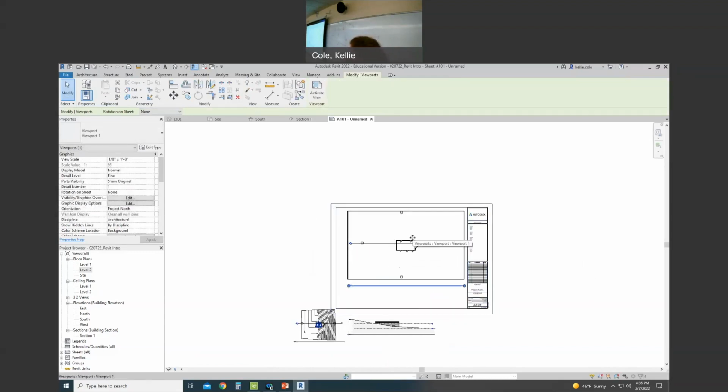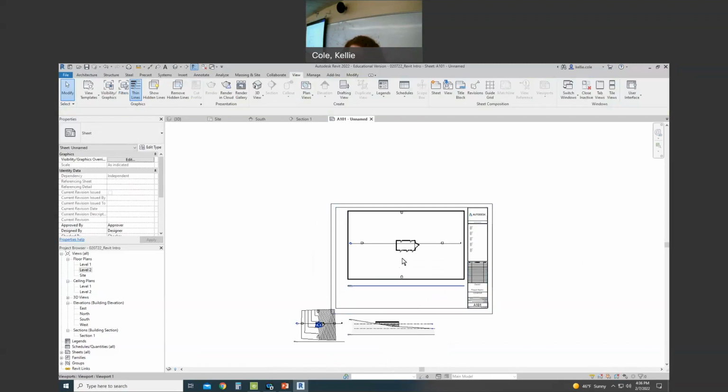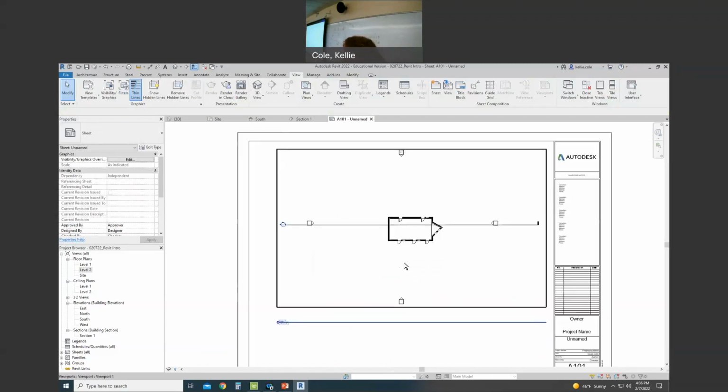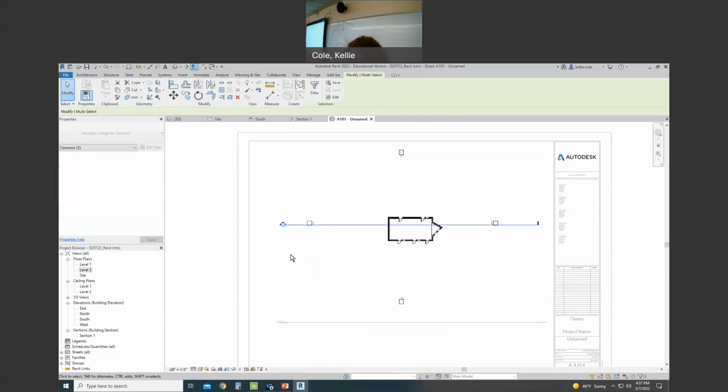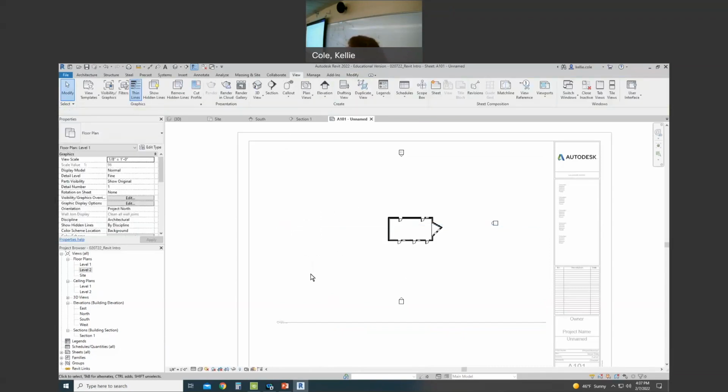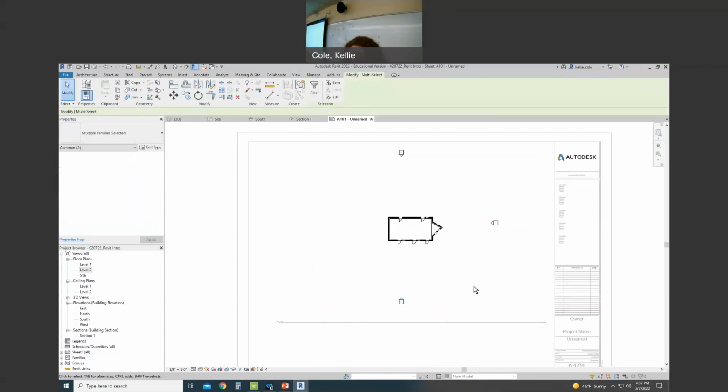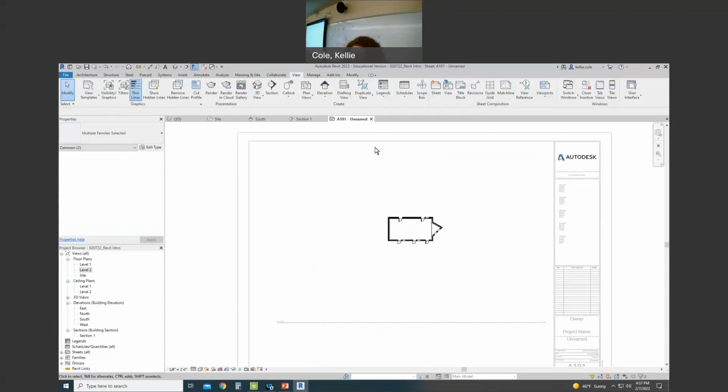And when you grab the floor plan in the sheet view, it's going to grab the title and the drawing, right? Why don't we hide some things in here so that it's a smaller drawing? I'm going to double click in the view, and then I'm just going to select the objects I want to hide and type in element hide or EH. I'm just EHing everything. And then I'm going to right click,